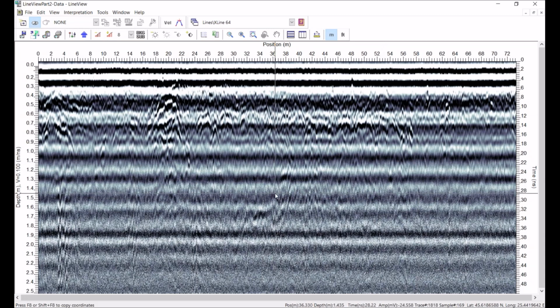which if you've seen my other webinars, this is system noise. There must have been a cable loose or something like that. Something metal was being energized near the GPR system and turned into an antenna, and it creates these things. So perhaps the person who collected this may have had their GPS cable dangling near the antennas or something like that. So regardless, it is something that we want to eliminate.